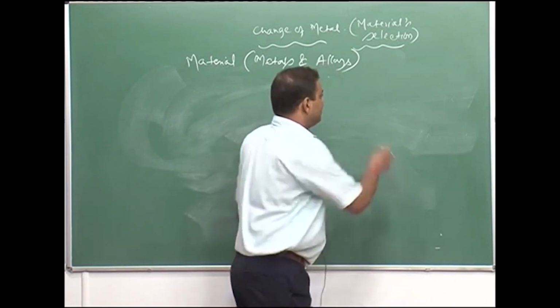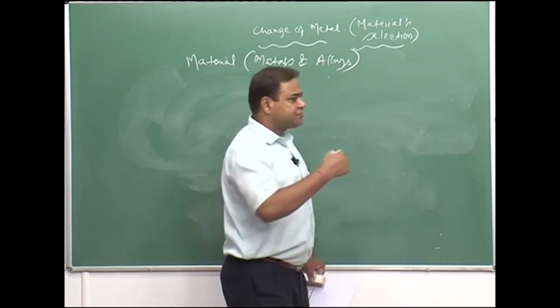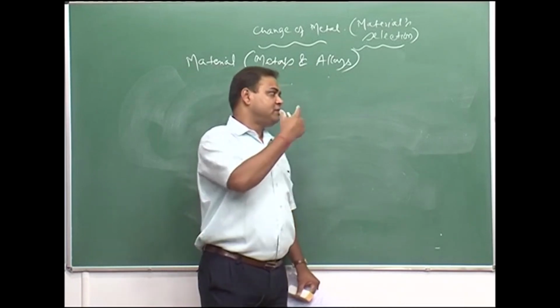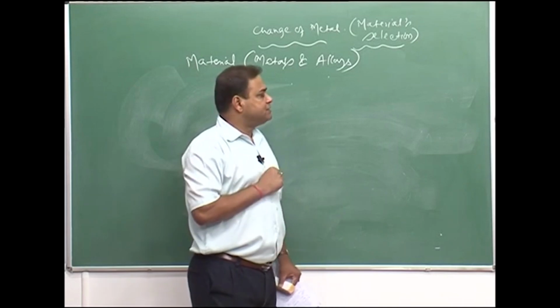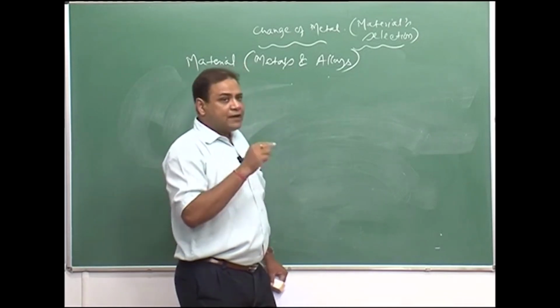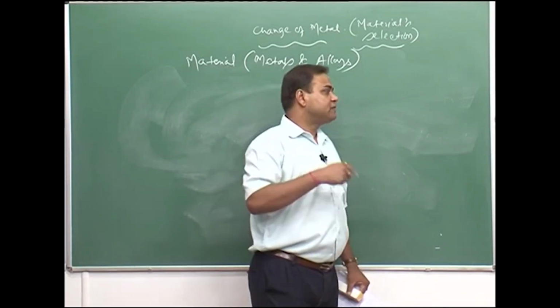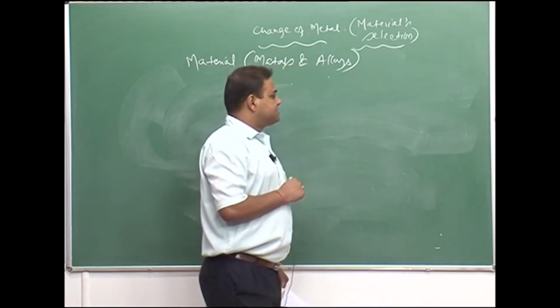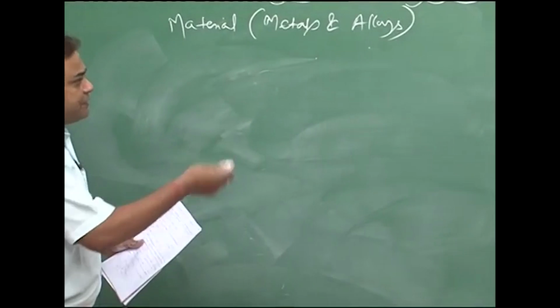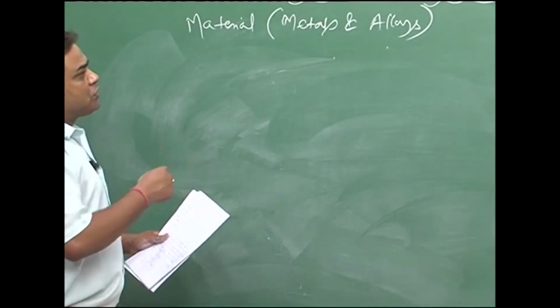Let us say molybdenum, we have already explained this, where the explanation is molybdenum is added as a carbide stabilizer in the material. Also we can add copper in the steel, which improves the adherence of the rust on the surface of the steel. Now, the alloying effect can definitely improve the corrosion resistance.